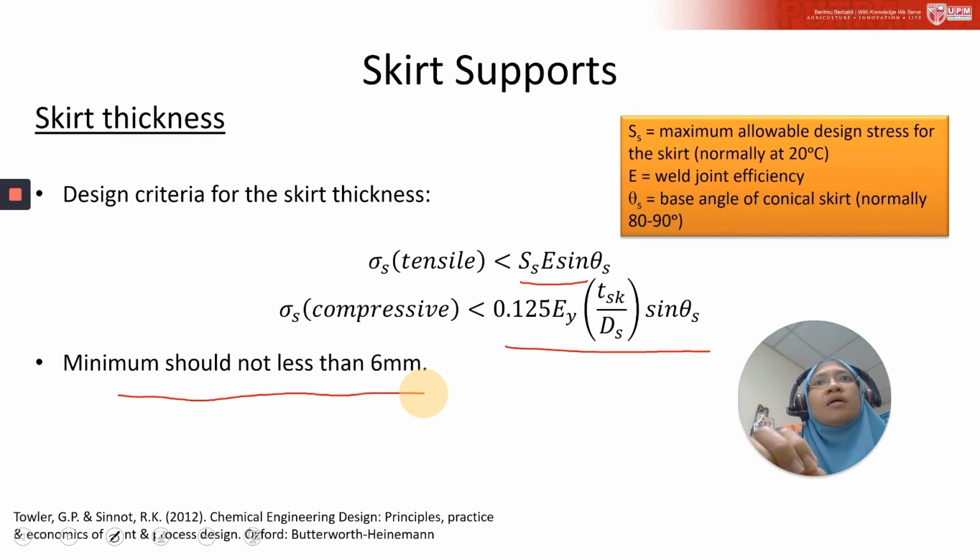And if the vessel wall will be at a significantly higher temperature than the skirt, for example if your vessel is used to store a high temperature liquid or any material, then you need to ensure that discontinuity stresses set up due to differences in thermal expansion are considered.